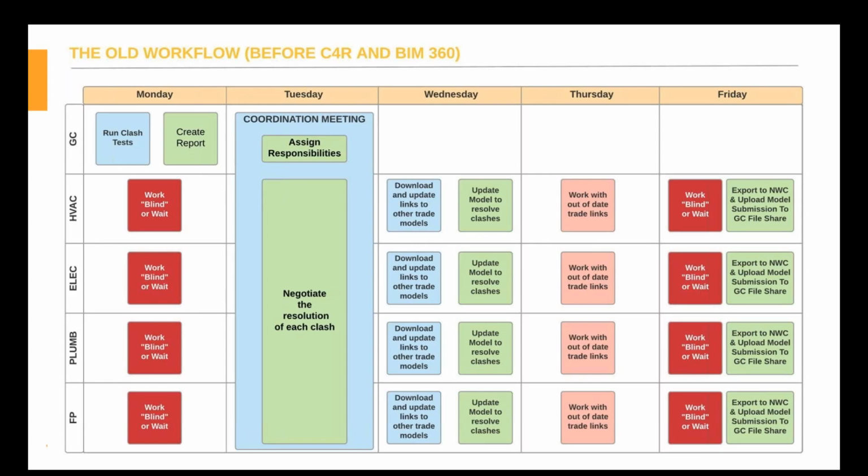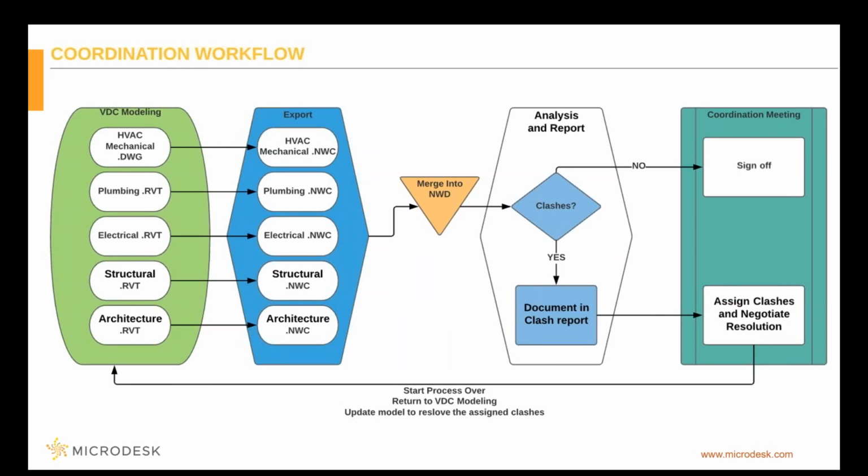So let's dive a little more into the workflow of this process. The VDC modeling would happen in AutoCAD or Revit. Here I have the HVAC mechanical contractor working in AutoCAD MEP, and everyone else is working in Revit. That still works. You can export everything out to NWC and merge those into a Navisworks NWD file.